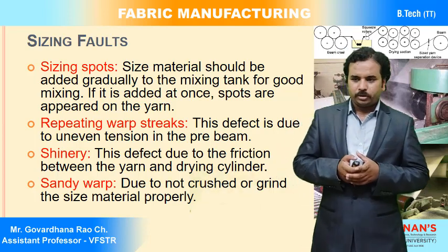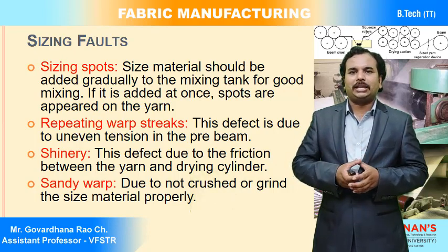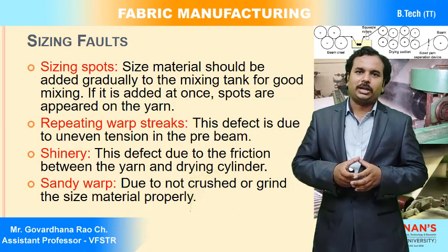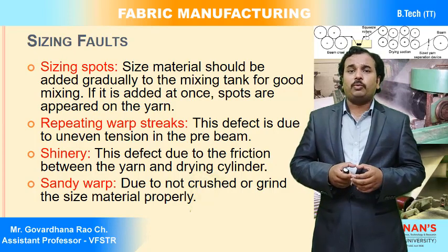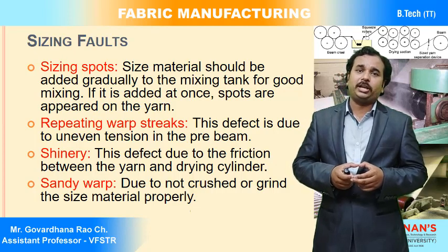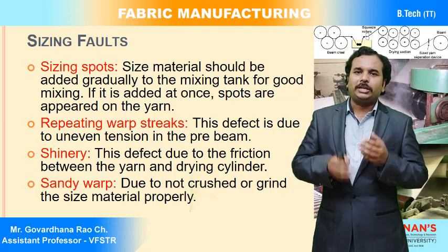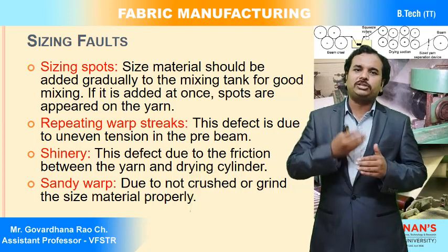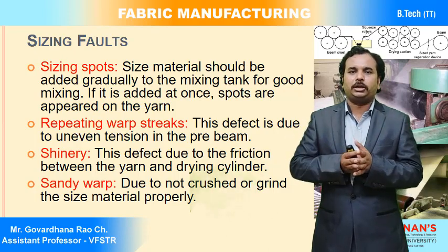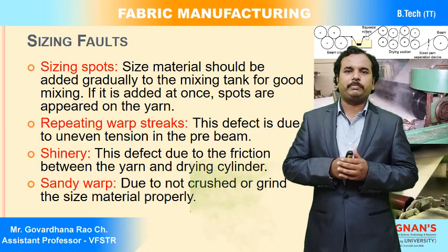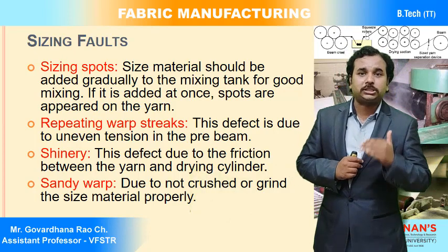Now, finally, in sizing we will discuss the sizing faults: what faults can be produced, and what the causes and remedies for particular sizing faults are. The faults should not be there, so we discuss the different types of faults we may get and how we can overcome them. We need to plan for that. You can see that the first one is called sizing spots.